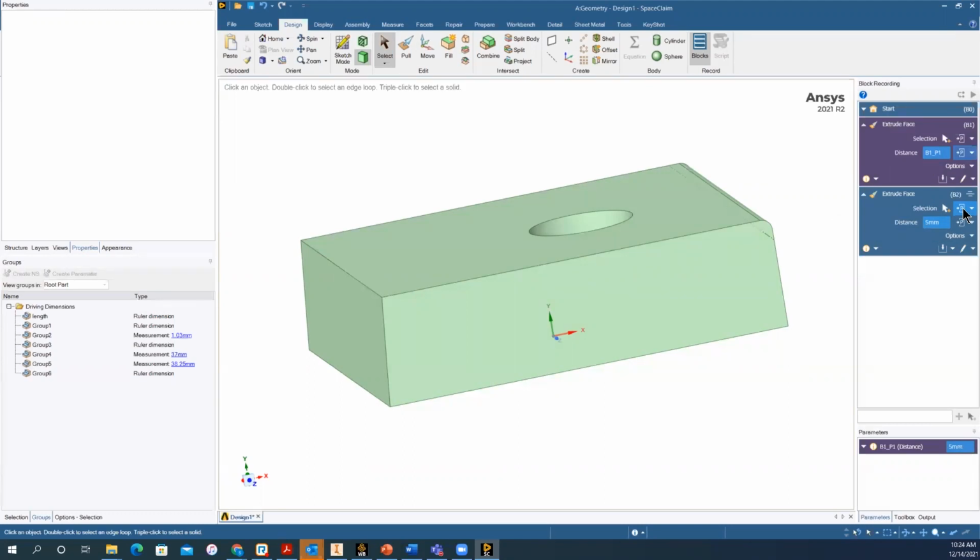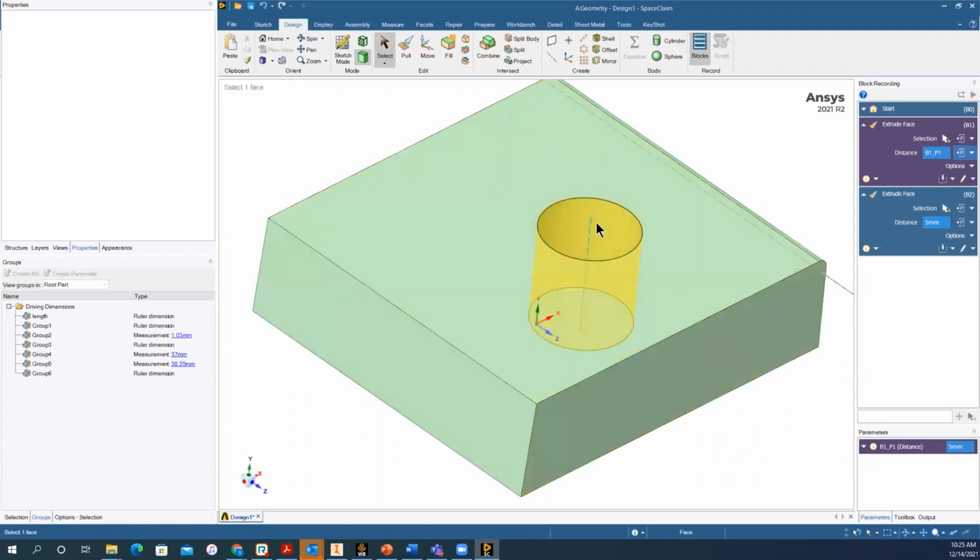The only thing is, the caveat with all feature-based trees is sometimes based on the constraints or relationships in your domain. There might be cases in which, say, for example, if you wanted to move this, you could, but there might be a case in your geometry wherein parameters in different blocks sort of interfere with each other or contradict each other. And in that case, there might be an error saying that, oh, maybe this particular block was not executed, and you would have to come back and then see, okay, what went wrong, or what is conflicting.